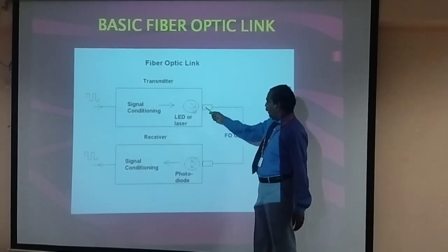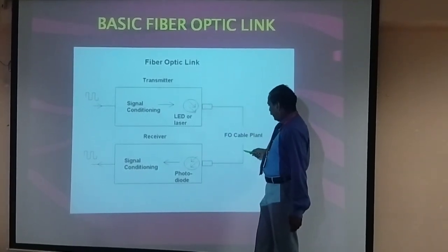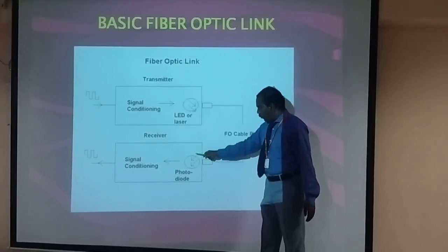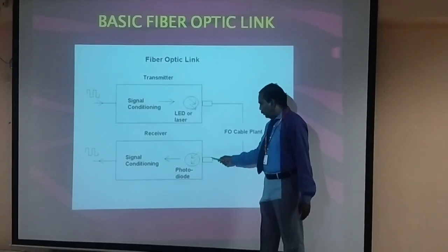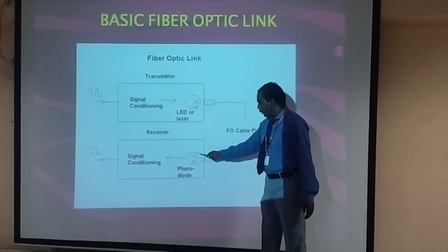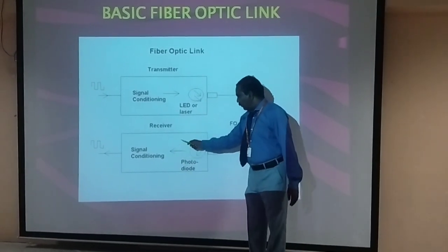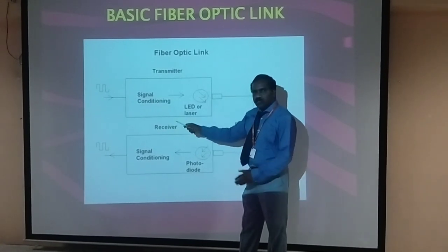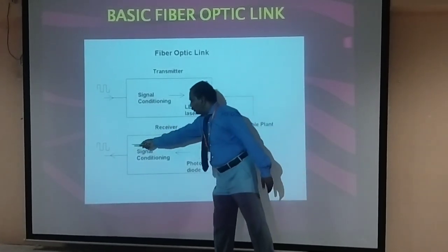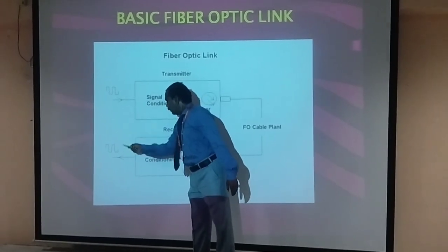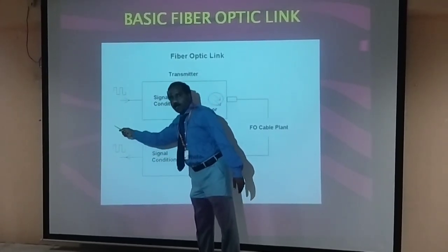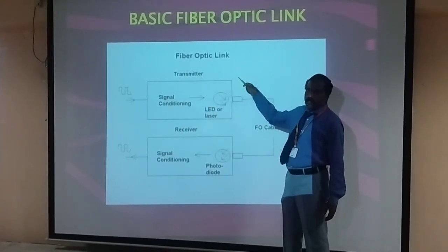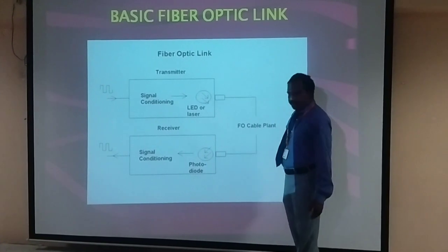The transmitter in turn transmits in the form of an optical signal. The optical signal is transmitted over the optical fiber, then it reaches the photodetector end. The photodetector converts the received optical signal into an electrical signal. Then it is further amplified with the help of the amplifier section. After that, the receiver separates the incoming signal into the original signal, so that we get the same signal reproduced at the output level. So this is a simple diagram of a fiber optic communication network system.